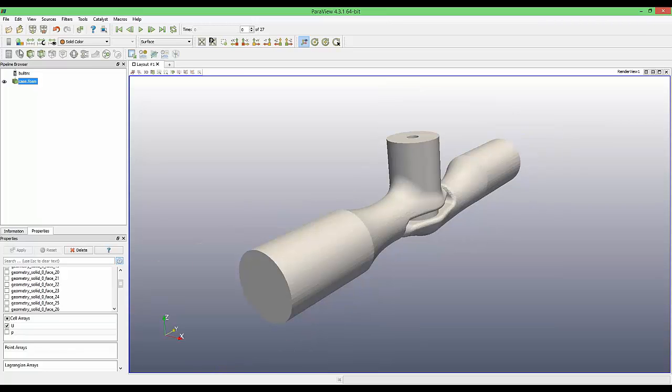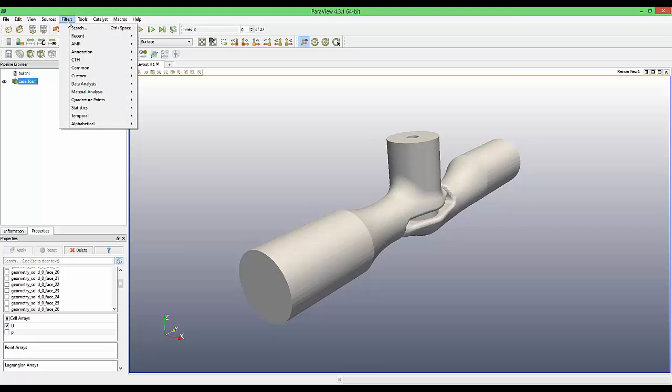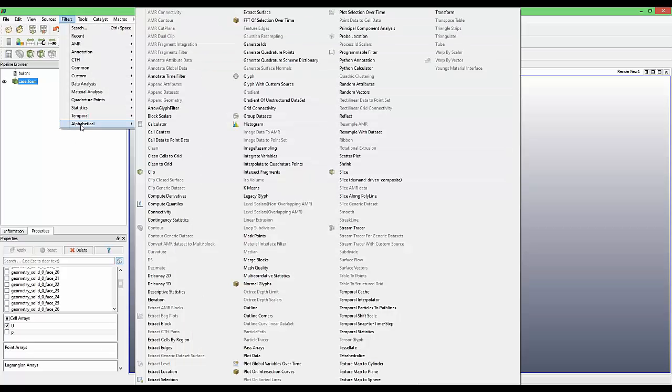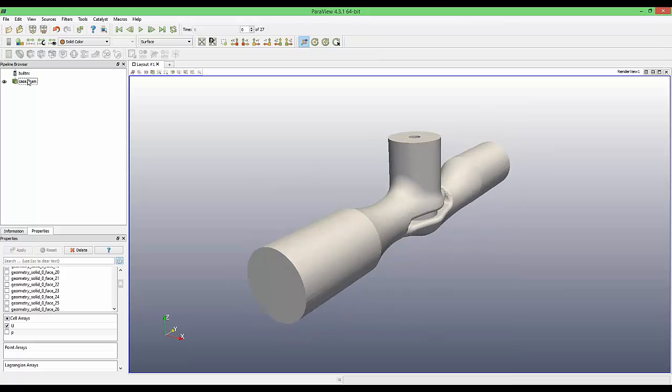We have the same setup as clips, slices on the default sets, and more. Lots and lots more filters. Most of the time you will be using 3 to 7 of them, but it's good to know that there is a big library of possibilities available under your fingertips to play with. Let's try to make the first analysis. We'll just go with case.foam. We'll apply our first slice.